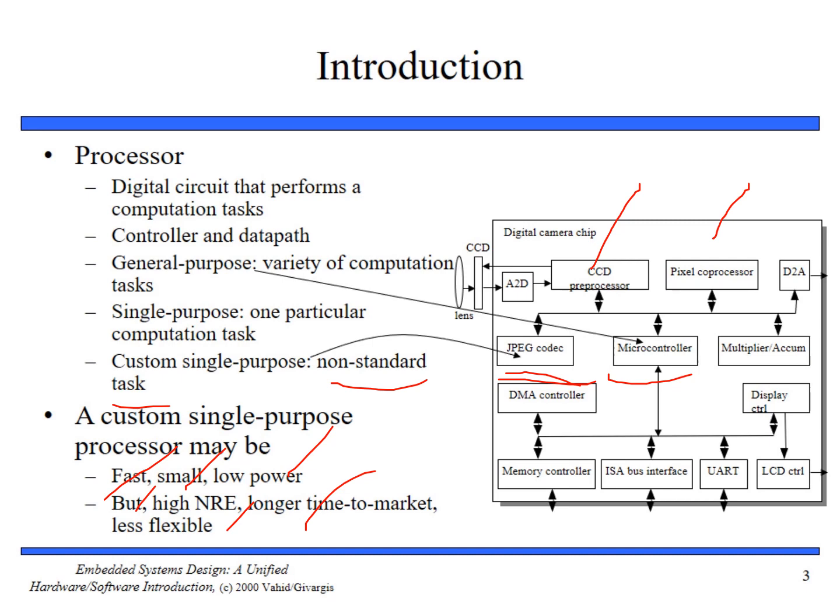As I have already told you, custom single-purpose processors are going to be faster due to fewer clock cycles resulting from customized data path, and due to shorter clock cycle resulting from simpler functional unit, fewer multiplexers or simpler controller logic. So everything is going to be very reduced in size, whether it's functional unit, control logic, data path, or multiplexer.